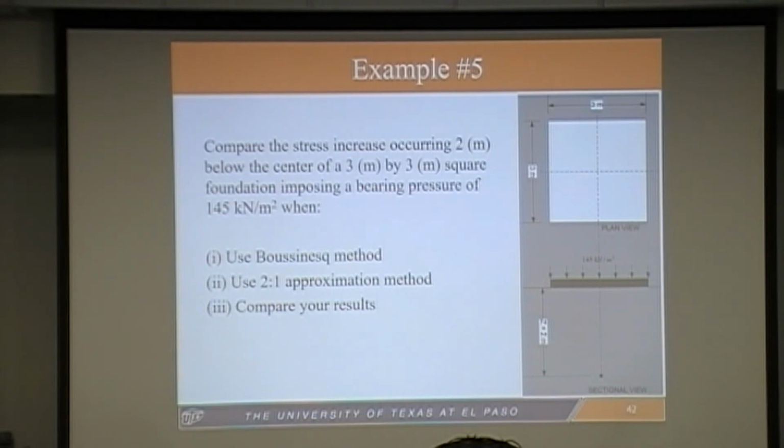Alright, based on this segmentation that we have here, which case are we looking at? We want to look at the stresses in the middle of that foundation. Case 1, 2, 3, 4. Case 1 was on the corner, case 2 was in the middle, right? So tell me what the B and L values are for this specific case. So 3 meter and 3 meter, right?